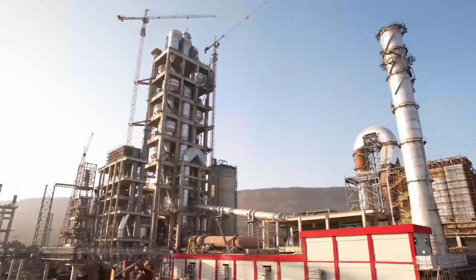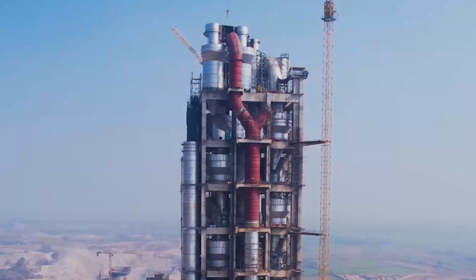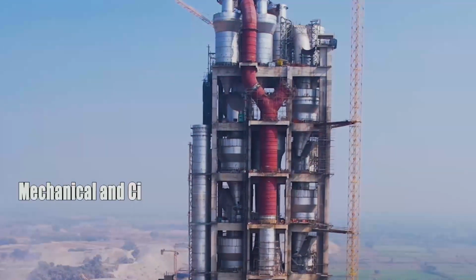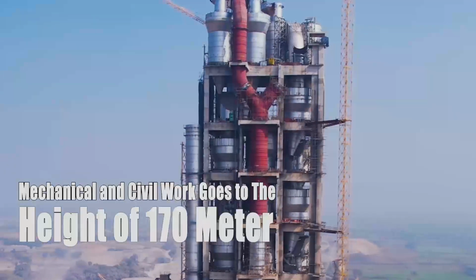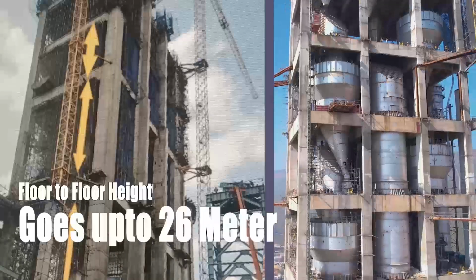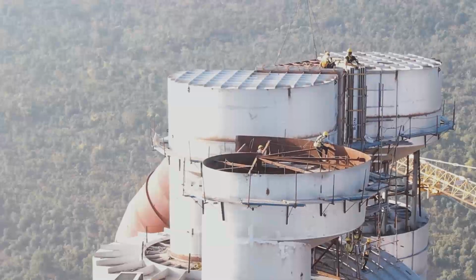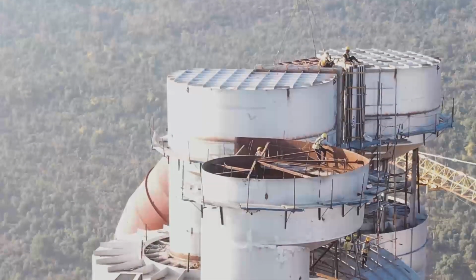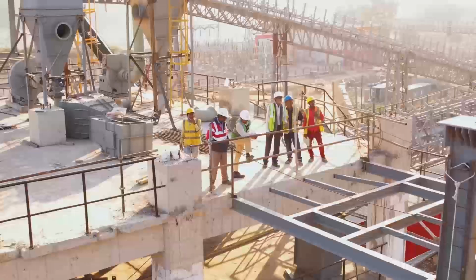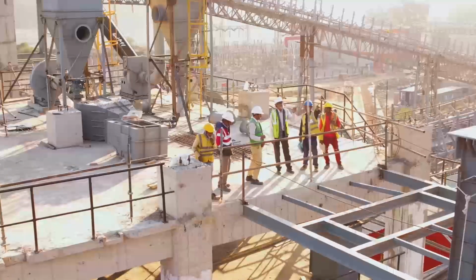Work at height is the major concern in cement plant construction. Preheater is the tallest structure in a cement plant. Mechanical and civil work goes to the height of 170 meters. Floor-to-floor height goes up to 26 meters. Any material falling from this height causes serious injuries. Deploying adequately skilled workers and proper planning is a must to complete the cement plant construction safely.